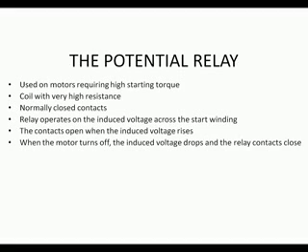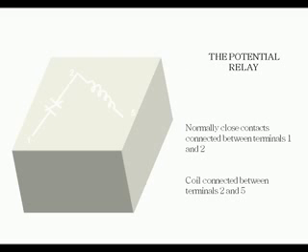The single-phase hermetic motors are hermetically sealed from outside air. In other words, they're welded into the case. They're similar to single-phase motors. They use relays to remove the start winding from the circuit, and they do not use centrifugal switches. They often use run capacitors for increased efficiency. They're designed to operate in a refrigerant atmosphere. In other words, we don't want any sparks. The motor terminals are identified on the outside of the motor as common, start, and run.